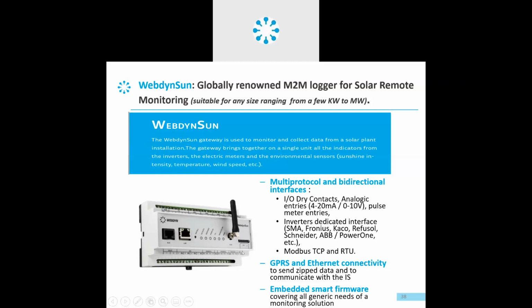You have inverter dedicated protocol. So again, coming to the dedicated protocol inverters, which are not Modbus. For example, SMA over RS485, which follows the SMA Net protocol, not Modbus in some cases. Some models of Fronius, which were IG models, KACO, Refusol, Schneider's Conext Core inverters, ABB 10 and 12.5 kilowatt rating inverters specifically, they follow Aurora protocols, which were from Power-One and others. These inverters connect on the dedicated RS485 port, which is RS485A, in a daisy chain manner.